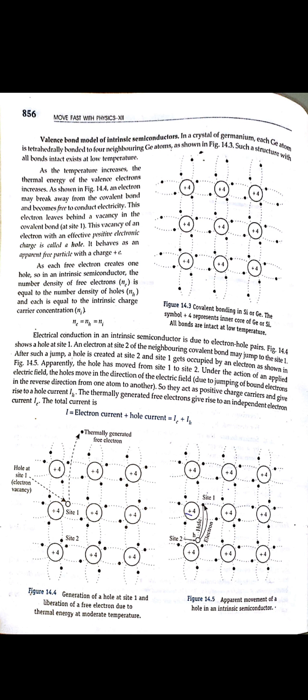So on the basis of that, we came to know that on increasing the temperature, the covalent bonds can break, the valence electrons can get free and move in the interstitial space, but they leave a space which was a vacant space, and that was a hole. So these holes and electrons are both responsible for the flow of electricity in the particular crystal. So in this semiconductor, the free electrons and the holes are both required for the flow of current.